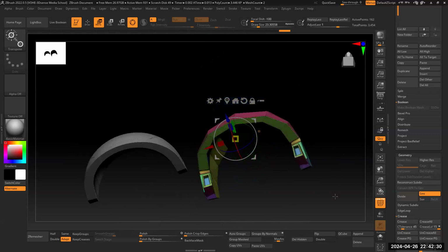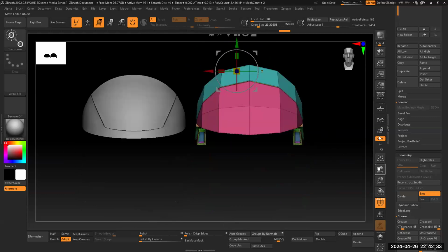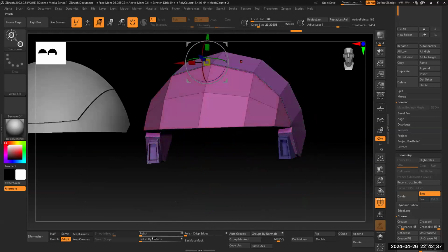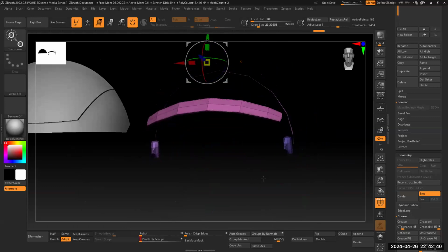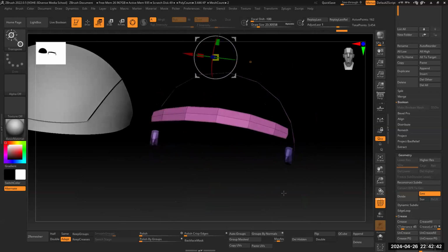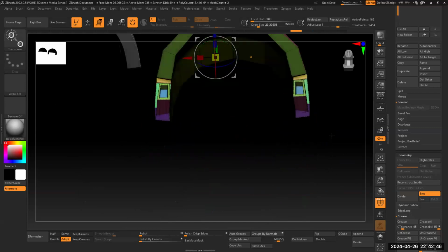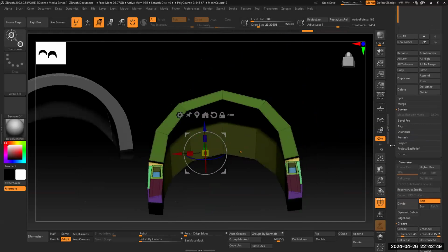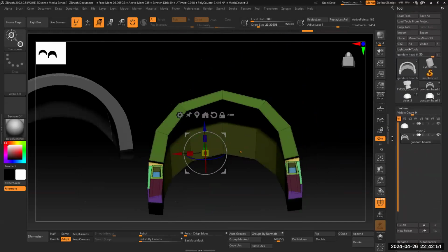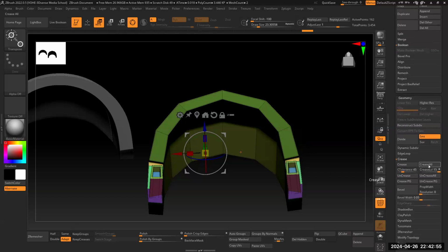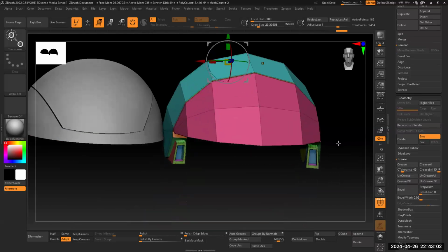And that allows me to choose each face or whichever plane that I want to affect, right? If you don't, and then you polish by groups, you tend to just kind of destroy everything when you smooth it, right? So we don't want that. We want to maintain that kind of shape. So we group by normals, and for extra bonus, under geometry, I like to crease my polygroups also, so that it maintains that shape.